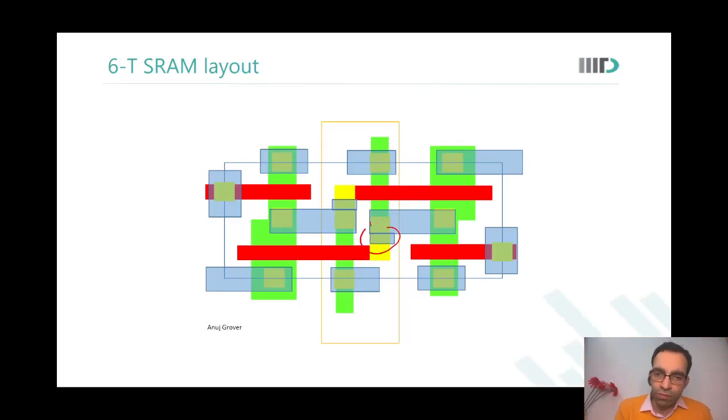Even these notches that you have, the M1 notches that we have shown here, even these notches could be violating DRC. But all this is allowed simply because we want to gain density, and it is technically possible because this is a very repetitive structure extending over hundreds of thousands of microns. So we can do something about the optical proximity correction over there. If this was not that broad and that widely used symmetrical structure, one would not want to do it. It's much riskier.